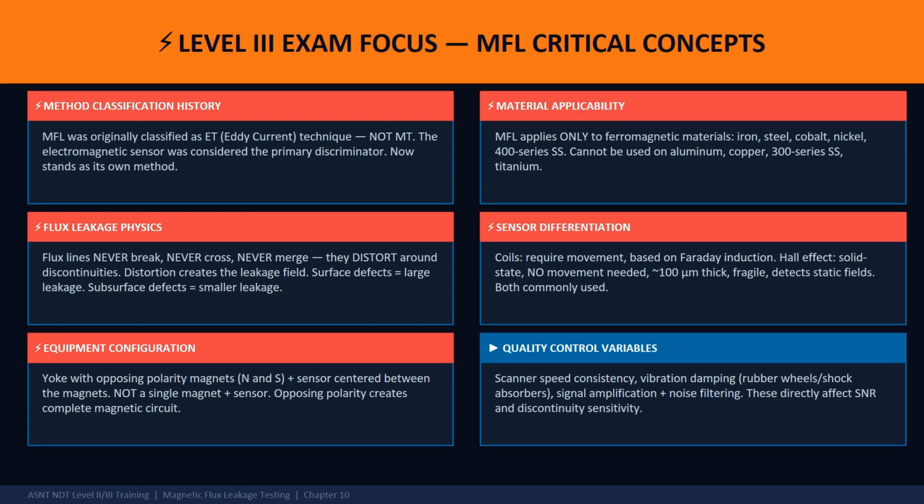Here's a Level 3 challenge. Suppose your MFL scan shows excessive false calls. What should you investigate first? Think like a Level 3. Possible causes: excessive vibration, poor calibration, bad threshold settings, low SNR. That is the mindset examiners expect.